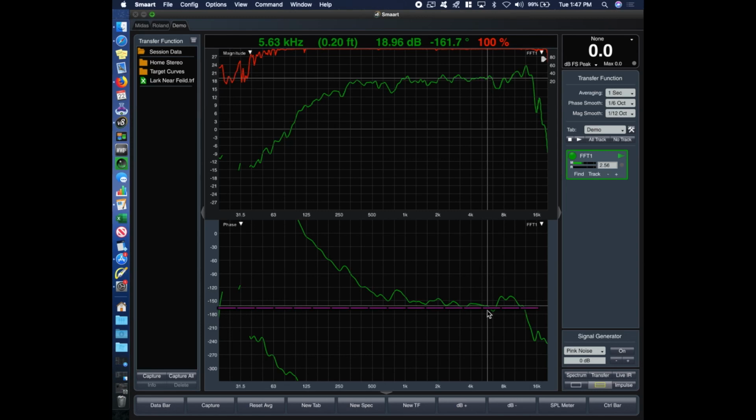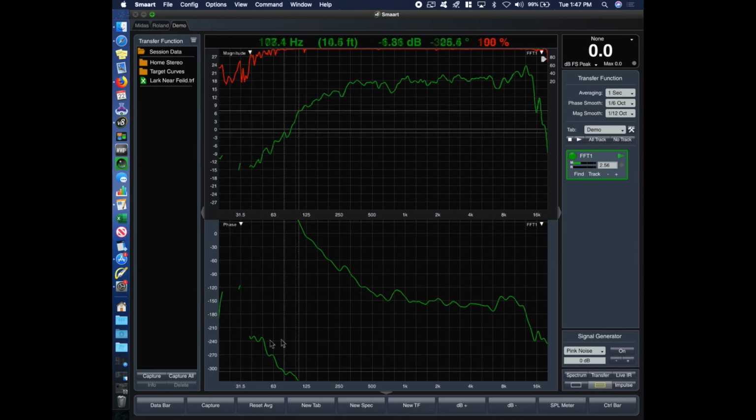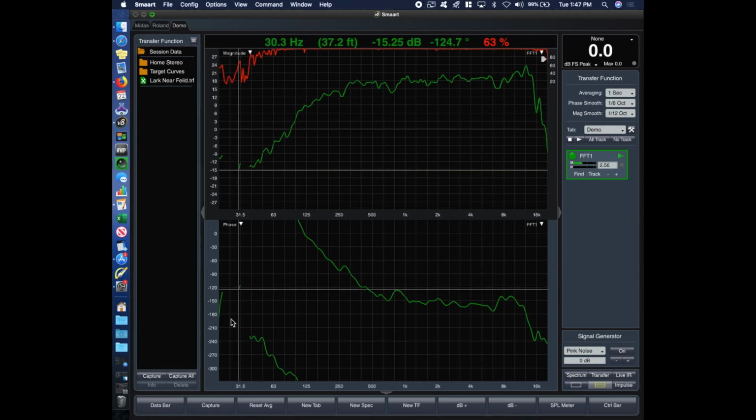And this kind of goes into the rabbit hole discussion that Frank and I were about to go down with these reference mics, the DBX reference mics that I use and the university owns. They're all wired out of polarity from every other measurement mic in the industry. So because of that, when you use these, your nominal phase, or your phase that is arriving in time, is not going to show up at the 0 degree mark. It's going to show up far closer to the 180 degree mark because of that polarity reversal. Does that make sense? And you guys all know that phase and polarity are not the same thing.